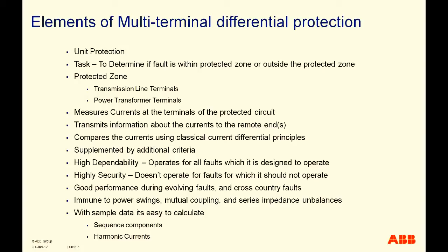But in practical terms, there are several scenarios in which identifying whether the fault is within the protection zone or out of the protection zone might be a little bit tricky. Determining whether the fault is within the differential protection zone or out of it is a task, and we will talk about it in detail, what type of techniques we use in ABB protection relays to determine whether the fault is within the zone or out of the zone.